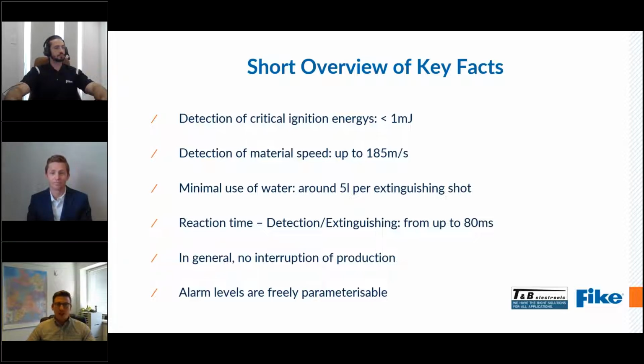If we extinguish a spark in the suction pipe, there is 1 liter per second, and we extinguish into the suction pipe for 5 seconds. So there will be 5 liters in one extinguishing shot. The reaction time between detection and extinguishing is from 80 milliseconds, and it depends on the diameter of the suction pipe.